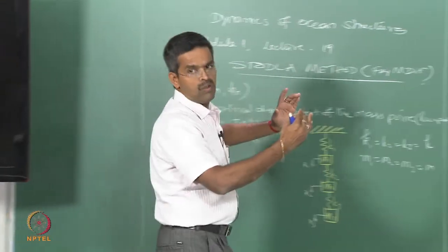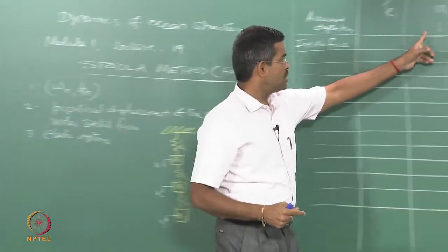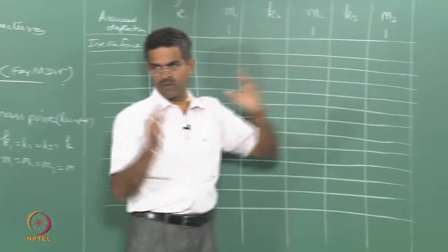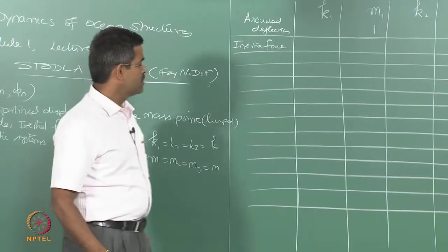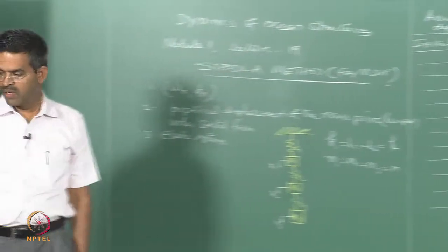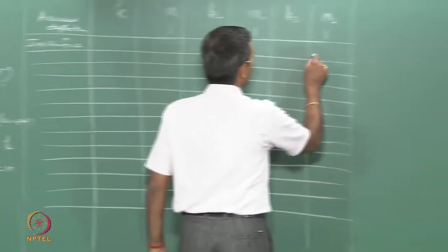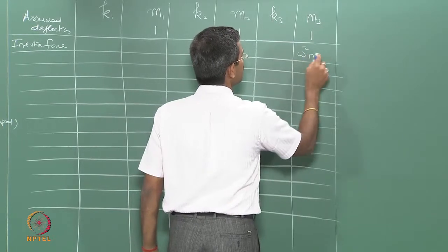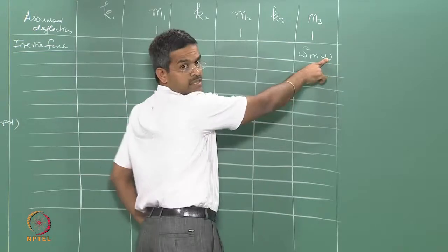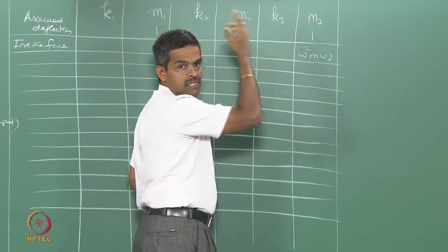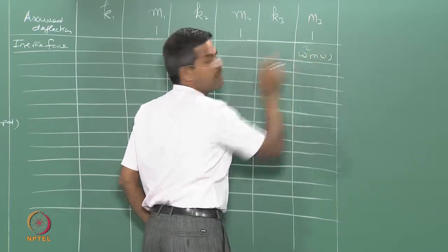So look at the absolute value, we are looking only for the proportional displacements between the masses. We can look at the absolute value because all of them are going to be negative, we need not look at the negative sign. So I should say now omega square m of 1. Omega square times displacement is the acceleration, minus sign I am not considering, m is this m.